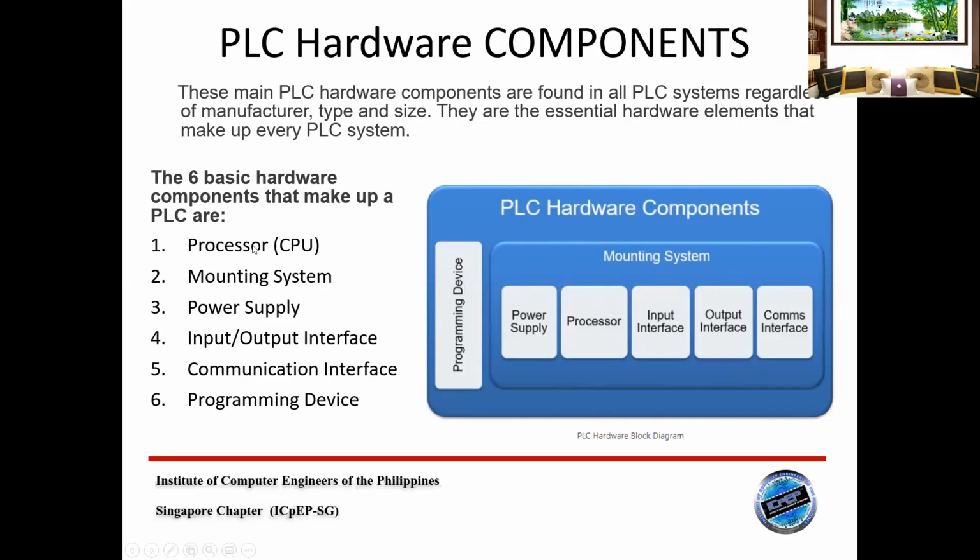So the processor is also referred to as the PLC controller. In the PLC, the CPU is responsible for controlling all the PLC activity. This includes program scanning, such as ladder logic, program execution, handling data storage, directing data flow, and controlling communication among the various interfaces. So number two is the mounting system, which provides the means of physical connection of the various hardware components of the PLC.